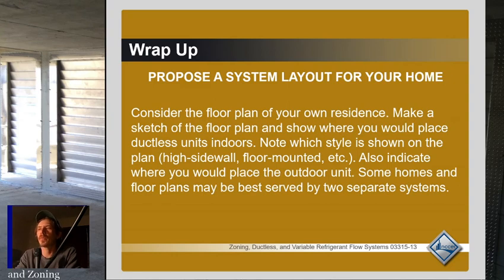The other problem that you run into with mini splits a lot when people aren't thinking about the design is oversizing. Okay, and mini split manufacturers are doing a better job of designing around this problem, but often people will size these mini splits based on very, very inaccurate rules of thumb that they even put on the mini split websites and stuff. If you've got a 400 square foot room, then make it a 1-ton mini split or whatever the case may be. That's not a good thing to do.